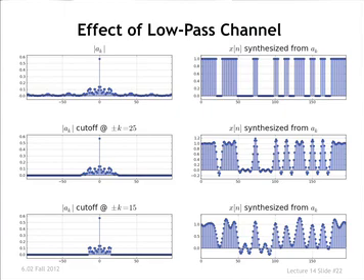In the first case, everything goes through, there's no distortion, you get the same thing back again. In this case, the channel has a cutoff that zeroes out all spectral content outside of some frequency range. So it's a low-pass channel whose bandwidth is not enough to take the spectral content of what you're feeding across. So what do you expect to happen?